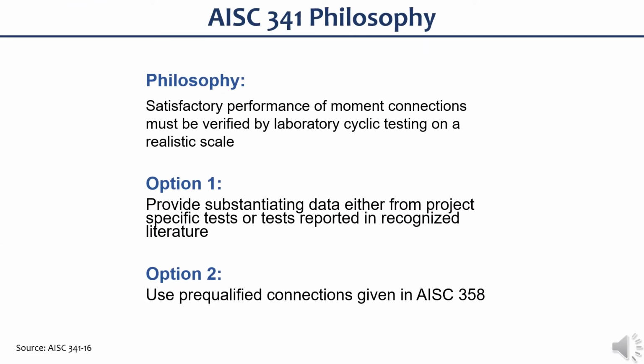The behavior of SMF connections, especially the initiation and propagation of fracture under severe cyclic loading, cannot be reliably predicted by analytical investigation alone. Therefore, AISC 341 adopted a philosophy that performance of moment connections must be verified by laboratory cyclic testing on a realistic scale.